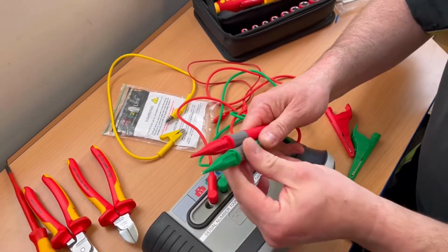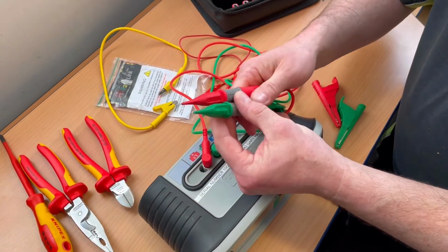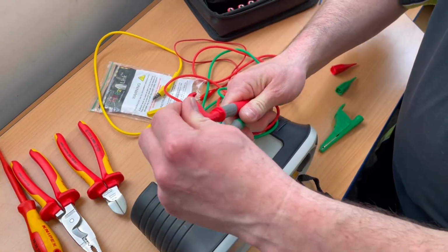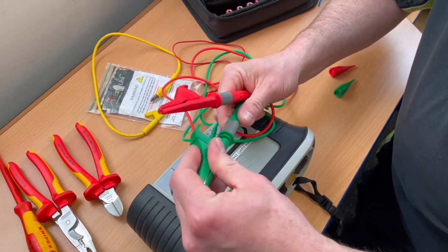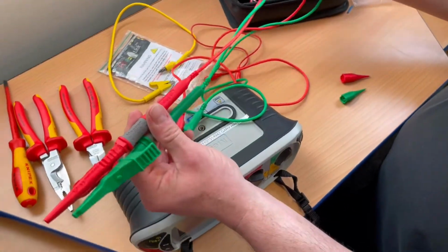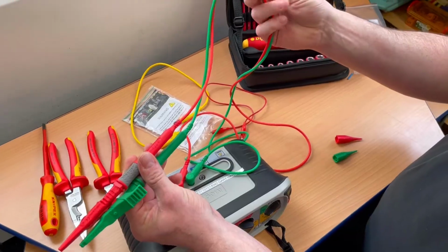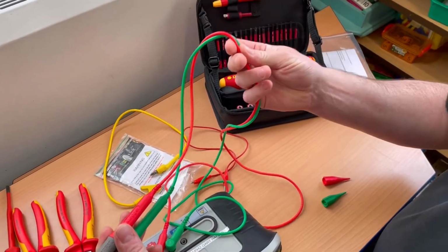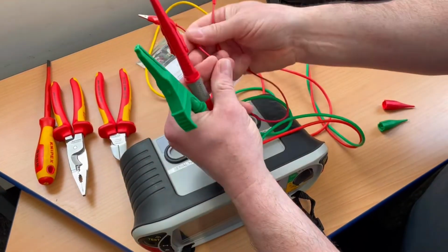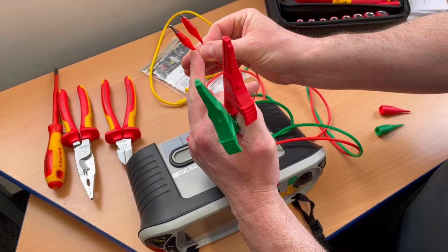And now we're going to remove the resistance of these. Well, we've currently got the tips on them, which I will use, and I will use the crocodile clips as well. But just for removing the resistance, I'm just going to swap them over to the crocodile version of the leads, and then we're going to start by removing the resistance of the stuff that we're going to be using in circuit. These leads themselves are made up of copper, so of course they offer resistance and will need removing. And in early videos I did on the channel, I used to use a link like this in order to link in my consumer unit the line and CPC together.